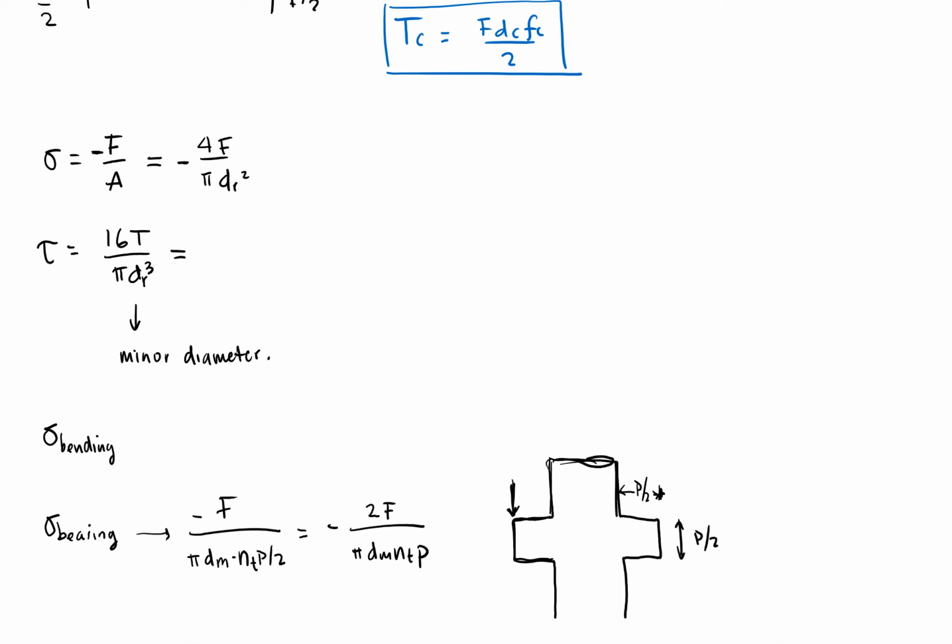And finally, for bending, I need my M over I, or I over C. Let's rewrite this. I over y, this would be M over this to get my bending. It would be the base h squared over 6. So this is just like 1/12 b h cubed, but then the y would just be h over 2.